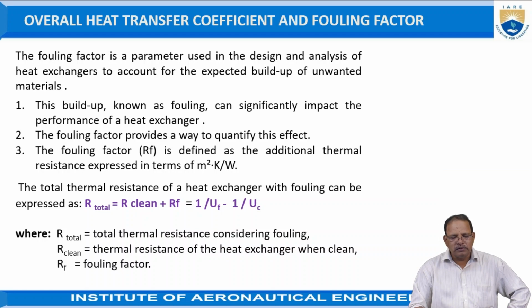So the build-up, known as fouling, can significantly impair the performance of heat exchangers. When the thickness of the fouling is more, the performance of the heat exchanger decreases. The fouling factor provides a way to quantify this effect.